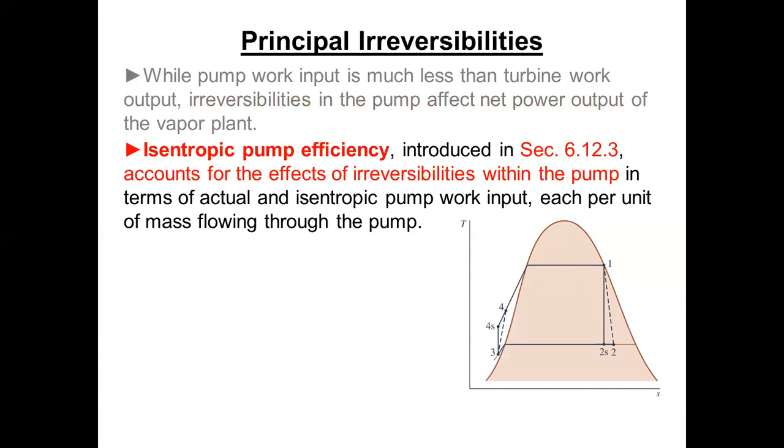So in reality, let's say at Kingston, the steam pressure is nominally 1800 psig. So that's 1815. They call it 1814.7 or 1815. The power plant people usually just go ahead and call atmospheric pressure 15. But let's say that isobar is probably in the order of 2000, 2100, maybe even 2200 coming out of that pump. So that's what really establishes the high pressure in the system, what we come out of that feed water pump at. And then it goes to the boiler.